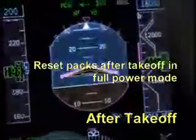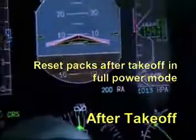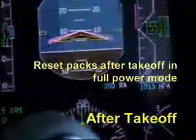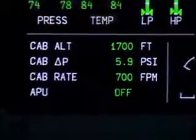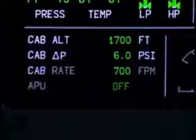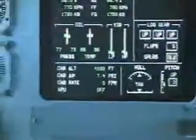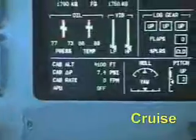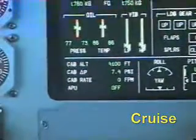After takeoff, observe that cabin altitude is maintained at about 400 feet below takeoff altitude to satisfy internal laws in the controller. Observe the point where cabin altitude begins to climb. Anyway, this condition should not last longer than 15 minutes. Once in cruise phase, the cabin will stabilize at the lowest possible altitude, which is proportional to the cruise level.